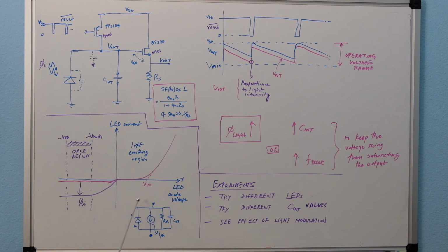In terms of the LED model itself, it looks something like this, with a standard diode and a photonic current source, IPH, and two parasitic elements, R shunt and C shunt capacitance. The capacitance really comes into effect when you're talking about dynamic operation, AC signals and modulation. In this particular example, we are going to use DC light, light that is not changing, so we won't have to worry about the C shunt as such, or the bandwidth of this device.